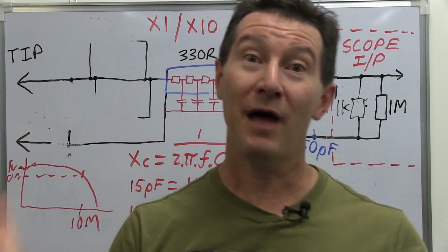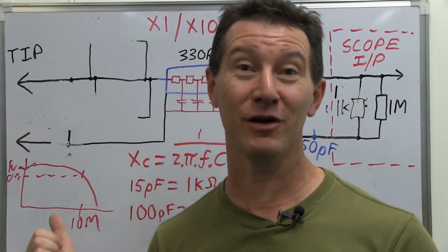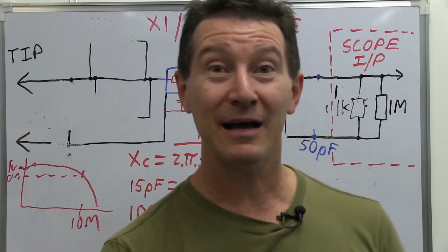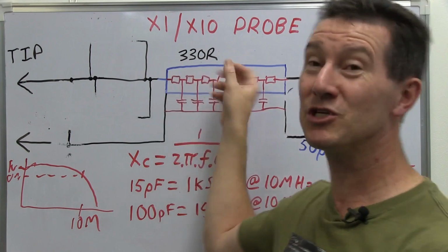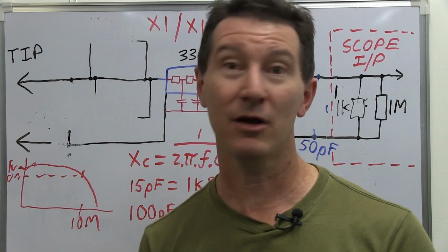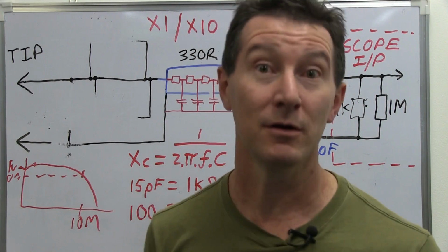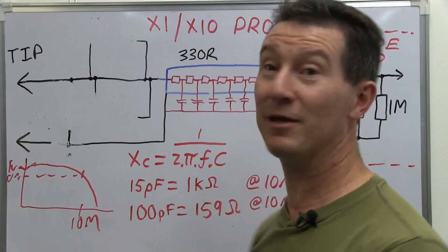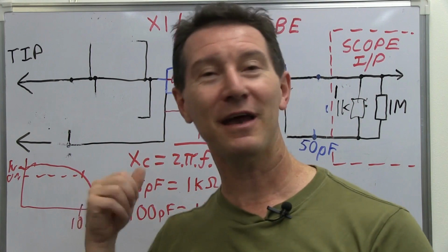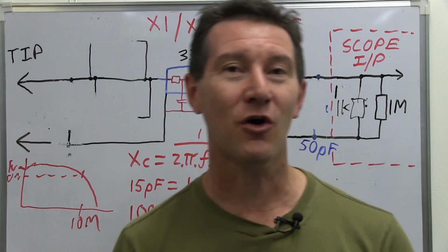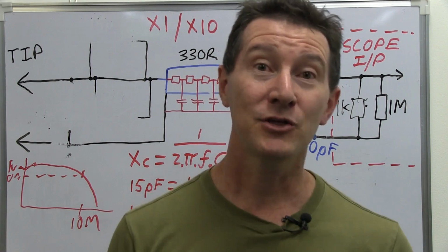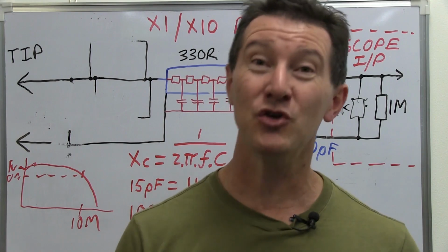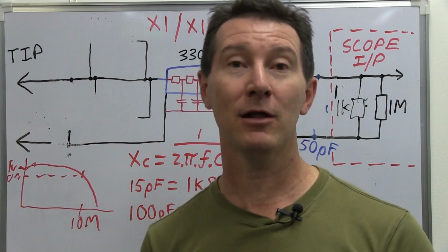Whew. Well, that was a lot of talk just to get to the simple conclusion that an oscilloscope probe coax actually has a lossy transmission line resistance in it. I could have just told you that at the start and saved you 15-20 minutes or something, but I hope you found that interesting, and that is why these ×1 probes have a lower bandwidth than a ×10 probe, by an order of magnitude or greater. It's something a lot of people don't know.